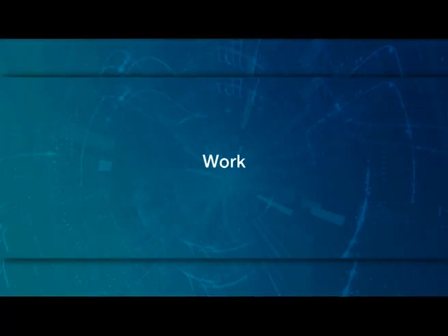Then work. If a system undergoes a displacement under the action of a force, work is said to be done. If a system as a whole exerts a force on its surroundings and a displacement takes place, the work that is done either by or on the system is called external work. When the external force acting on a thermodynamic system is in the same direction as the displacement of the system, work is done on the system. The work is regarded as positive. When the external force is opposite to the displacement, work is done by the system, then the work is regarded as negative.